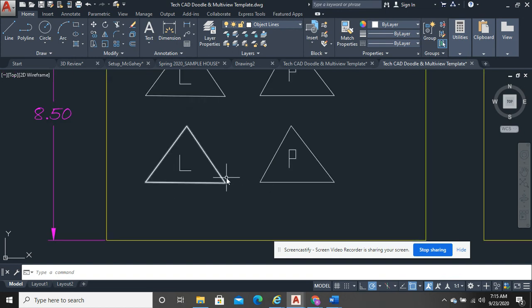So let's look at that offset tool and say, well, wait a minute, let's offset this triangle. Okay, so we're going to go ahead and offset this. So I click here. And in this case, I'm going to say something like 0.2, I think. Okay, so I typed in 0.2. Again, just to go back through that. Offset always remembers. So the next time you use it, see, I had already started to use it, and it says, do I want it to be 0.2? It remembers the last thing, so you always have to tell it. This time I'll use 0.15. You always have to tell it the distance you're offsetting something.